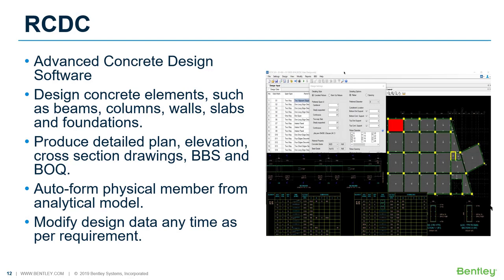So once you have performed the design for beam or column, it will automatically generate the bar bending schedule for you in .dxf format. So you can directly save the CAD file from this particular BBS.